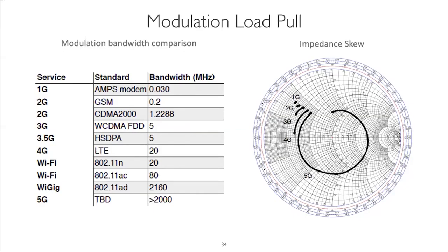So now the problem is, if we look on the right, this is just a hand-drawn example, but you could be presenting an impedance that's going once or twice around the Smith chart if you're looking at a 2 gigahertz signal. So how accurate is that, or how realistic is that, or even how usable is that when you're using a passive tuner and your impedance is basically going around the Smith chart a few times, right?